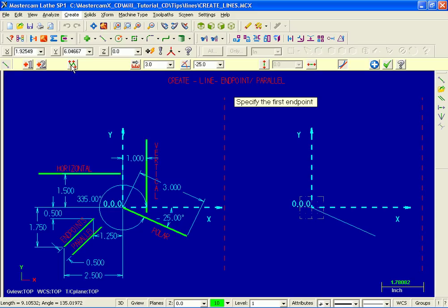Now what I'm going to do is slide on to the right. This is the section for length. Next door, angle. Now as we slide over to the right, this button will allow me to create vertical lines. Just to the right, horizontal lines. Moving over to the right will allow us to create tangent lines.